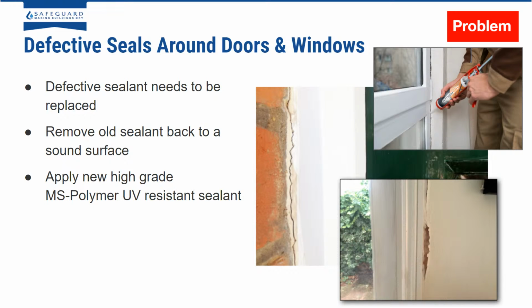I suppose this is a particular problem where you have timber frames, doors, lintels, windowsills, where obviously timber will expand and contract subject to moisture conditions, and if the sealant is too rigid, that's going to cause problems. So depending on the surroundings of the wall and the windows, you need to take into account what sort of sealant you're going to use. It's all about taking it case by case and trying not to use the same one for every single job.